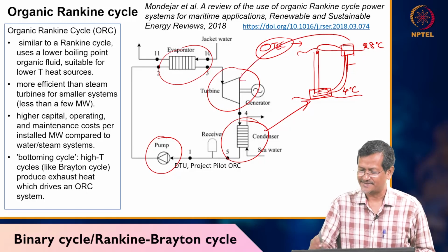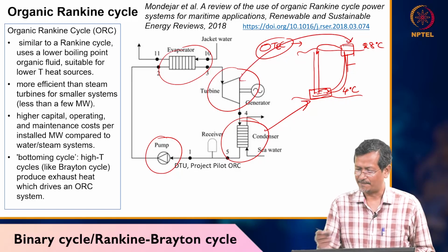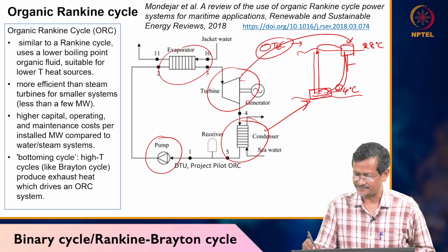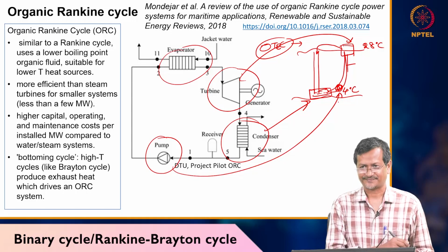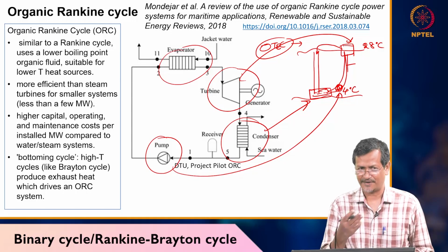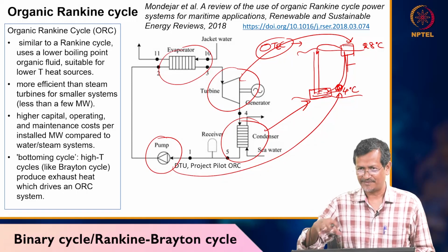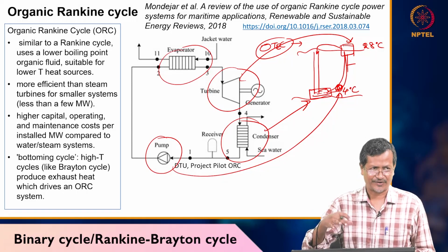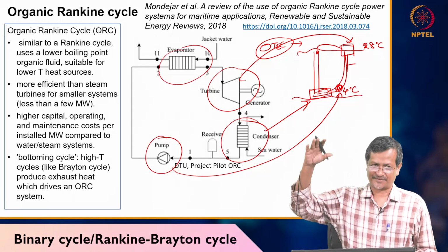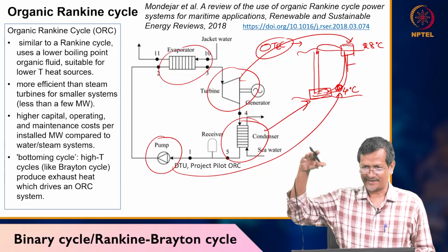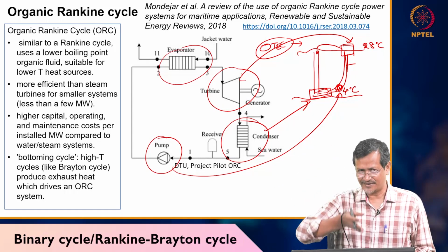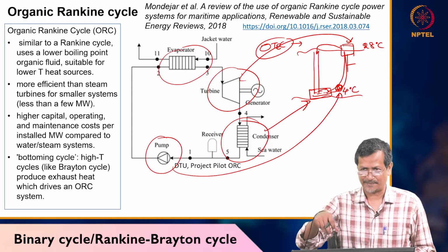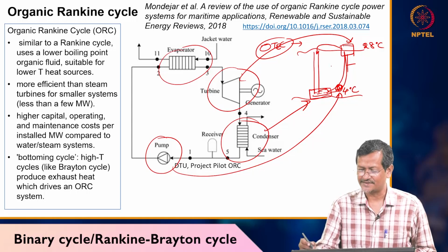Okay, the turbine is on the surface, and the pump, there must be a pump somewhere here. Okay, so the pump can be somewhere here, up, because the pump will be delivering only liquid. So the 4 degree centigrade temperature makes the refrigerant or ammonia liquid, then you pump it to the surface, run your turbine, then after the turbine again re-inject that fluid into the seabed through a pipeline. So that way the OTEC system will be working.